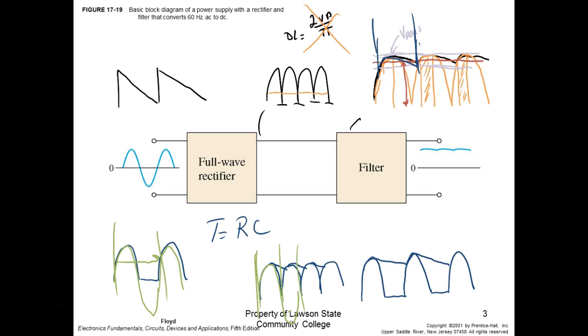I'm not saying that's the way it is. Go ahead. So the AC. This is half wave. This is full wave. So here's the input on full wave. But how many repetitions do we get out? There's one cycle and there's one cycle. So on half wave, my pulsating frequency would be equal to whatever I put on the input. On full wave, it's going to be twice whatever I put in.